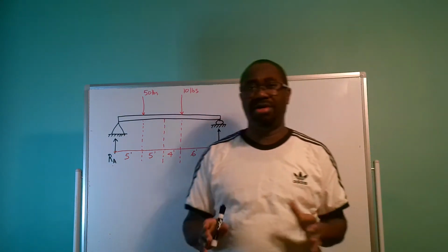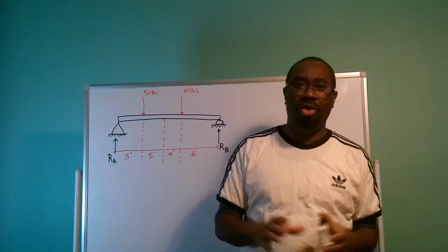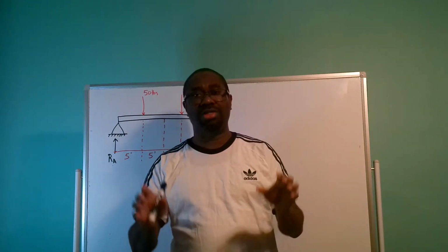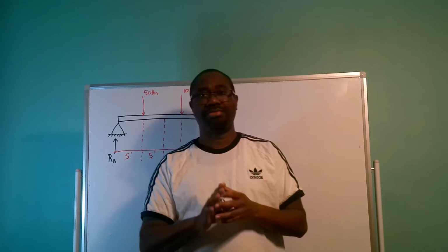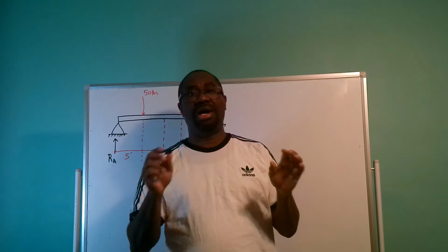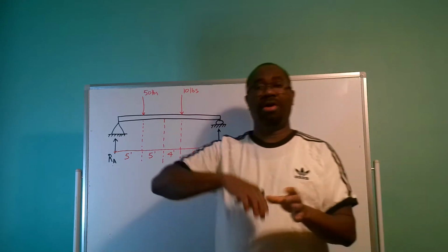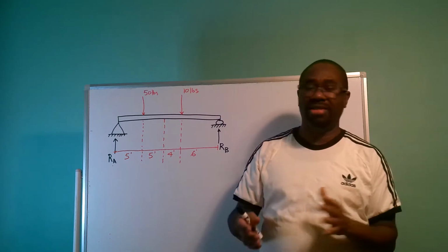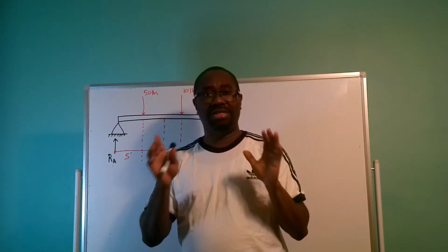In subsequent videos, I have reiterated to you that whenever the load is not acting at the center, you cannot use the formula to calculate the maximum bending moment. So this video is to demonstrate just that. I am going to calculate the maximum bending moment for a point load as well as a UDL for a beam that has a UDL and a point load that is off center.